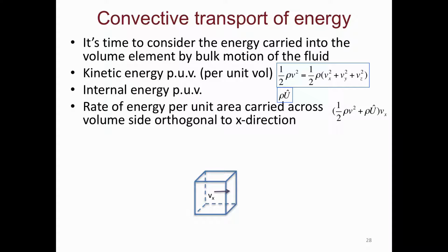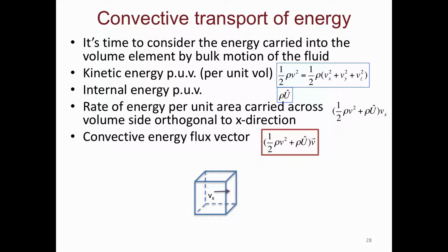Otherwise, all of the tangential parts are basically sliding around that volume and not going in. So they cannot change the energy that is inside the volume. Okay. So my convective energy flux vector, that is the equivalent of my rho VV from the equation of motion, is basically the energy that I carry times V. In rho VV, what I was carrying in was rho V. So rho V, V, right? And here I just have energy V. Yes? So it is the same structure.